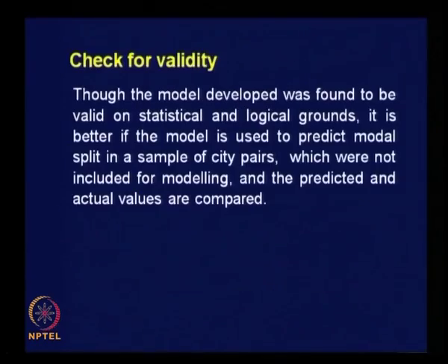And it is better to check for the validity of the model. In practice, it is better to apply this model for another situation where you actually know the modal share, use the model and get theoretically the modal share and compare the actual observed and model estimated modal share and check whether both are reasonably the same.